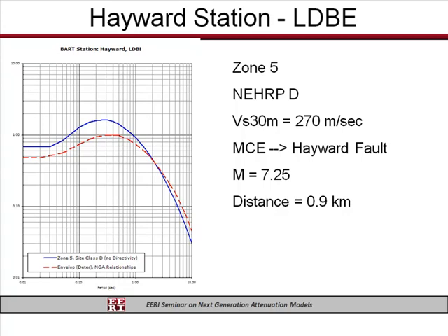One is the simplified 2002 approach in using the NEHRP amplification factors, and also the fact that, as Yusuf showed in his plot, the PSV, PSD actually doesn't really start to curve over as quickly as we thought prior to the NGA relationships.